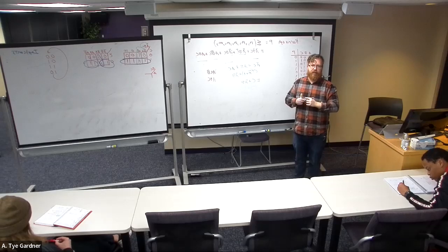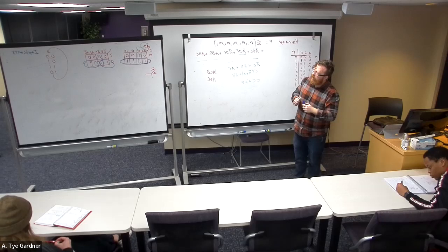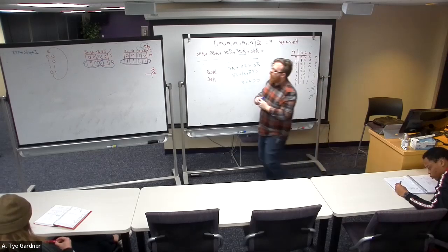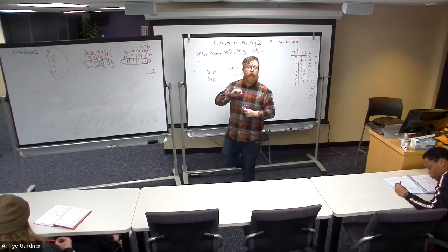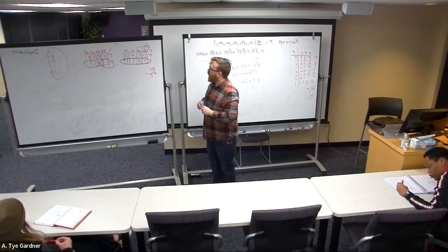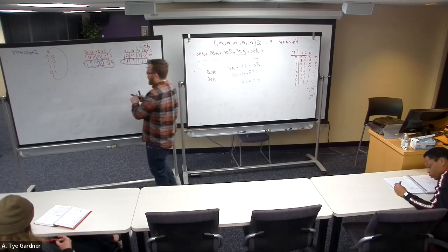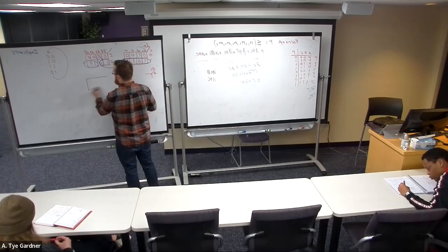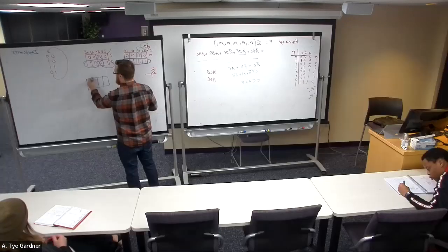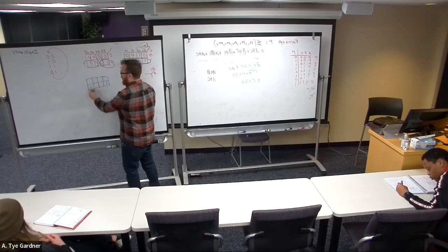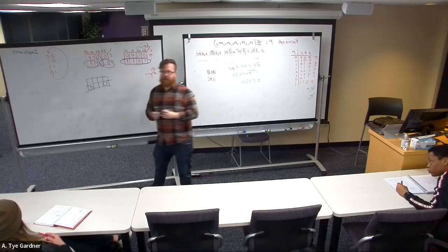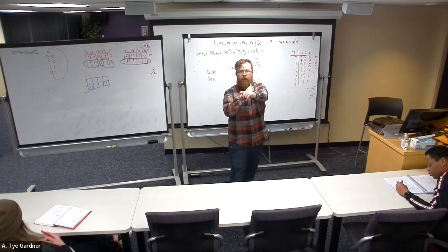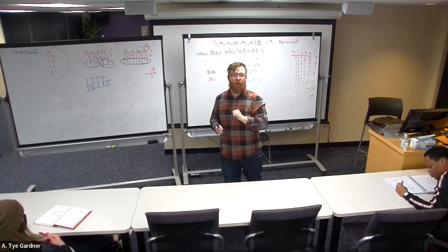I was just wondering, if on that bottom row of the K-map you have a one in the first and in the last, could you circle those two with zeros in between them? Like there's one on the far left, one on the far right. Can you draw a circle between those ones? Far left, far right? Yes, you can absolutely do that. You're just looking for the ones. We could do the zeros instead, but for now we're going to worry about the ones.